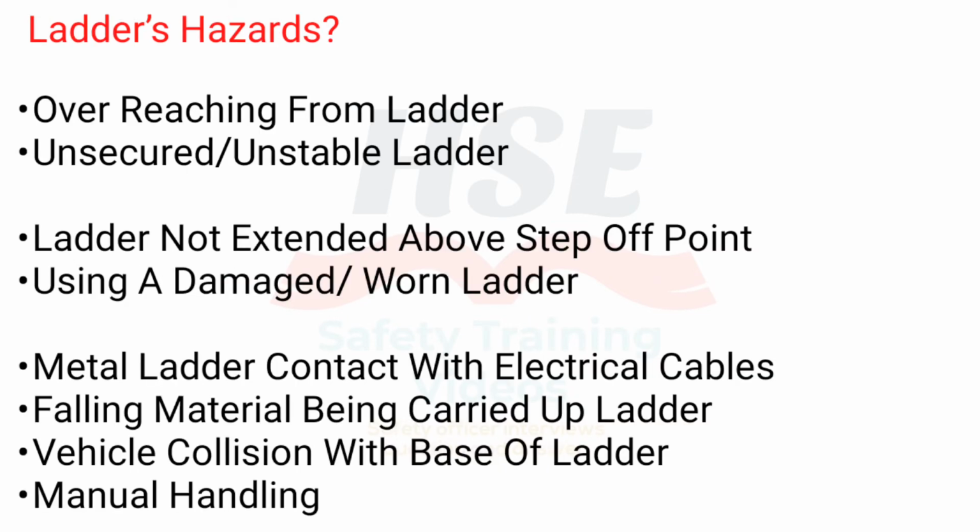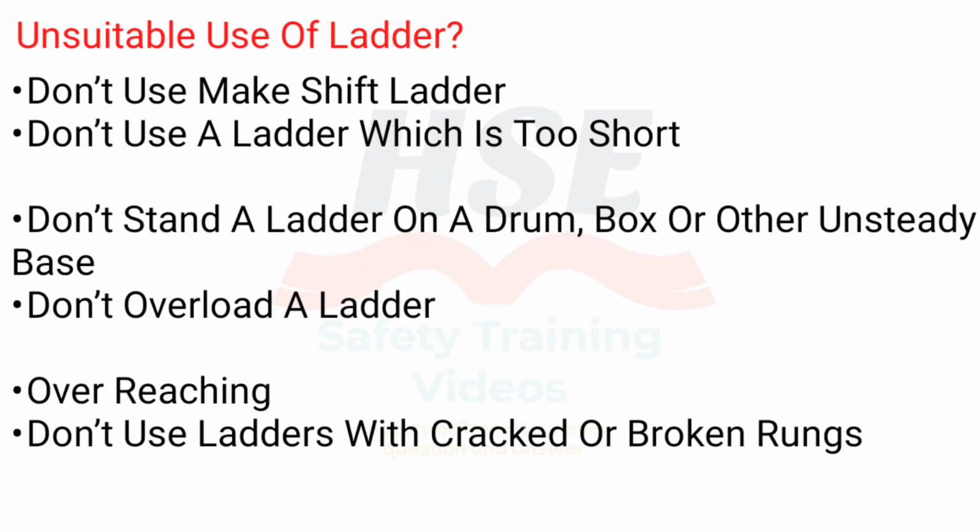Ladder hazards: overreaching from the ladder, an unsecured or unstable ladder, a ladder not extended above the step-off point, using a damaged or worn ladder, metal ladder contact with electrical cables, falling material being carried up the ladder, vehicle collision with the base of the ladder, and manual handling.